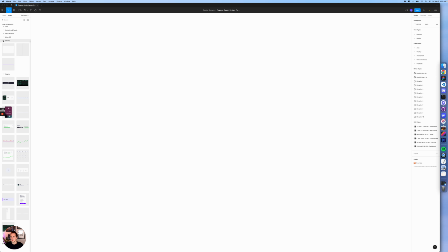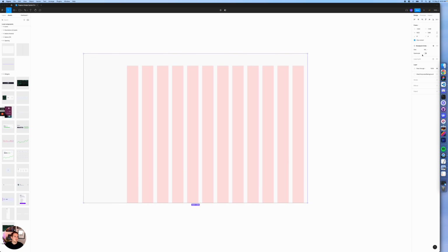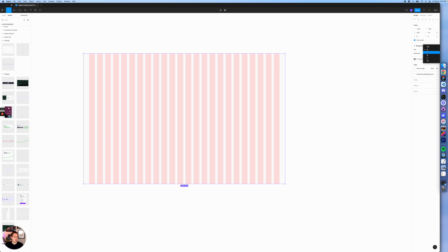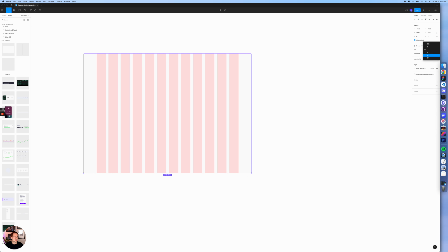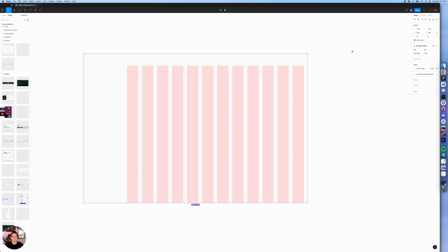And we're going to expand two areas. The first is spacing. And we'll see there's a component in here called breakpoint grids. And when we drag it in by default, it goes right to the extra large grid, which is dashboard. There's some others, editorial, landing page, all the way down to mobile devices, but we're going to stick for now with the XXL, and we're going to build it in regular mode, and then we're going to convert it over to dark mode. So for now, that's exactly what we need.